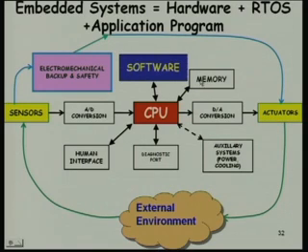As I was saying, in these kinds of systems, we will not really have magnetic memory, it is very rare in an embedded system to have magnetic memory. These are normally semiconductor memory but as we know, semiconductor RAM memory is volatile. So, how do you store data permanently? ROM is not being used very frequently now, it is getting obsolete. We have flash memory, like your pen drive, you have gigabytes of memory available in flash memory. So, what exactly is a flash memory?